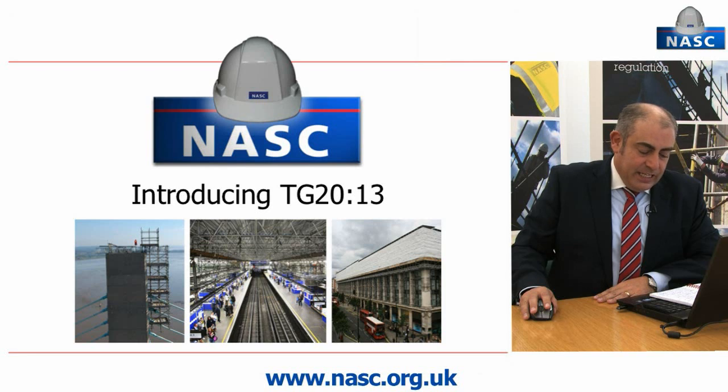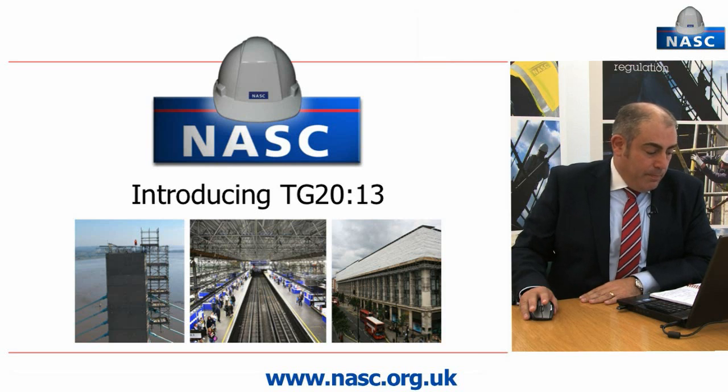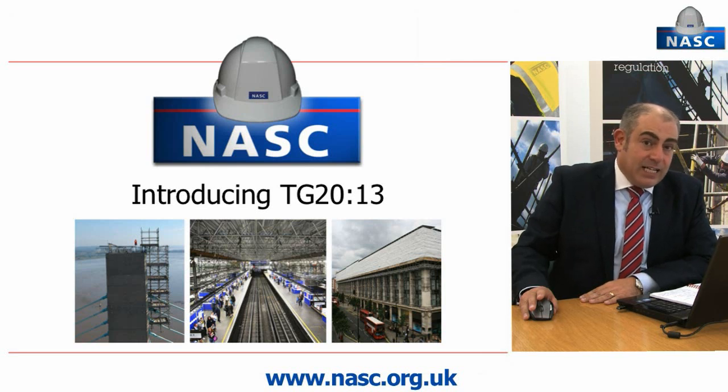It is recognised that the old Code of Practice, BS 5973, and subsequent editions of TG20 in 2005 and 2008 had a very narrow scope of standard scaffolds or basic scaffolds that could be built without design. This created many challenges for scaffolding contractors and notably placed a burden on the scaffolding industry and the limited design engineering resources. TG20:13 has been redeveloped to address these issues by extending the scope of standard scaffolds that can be built without design.